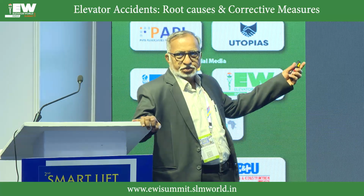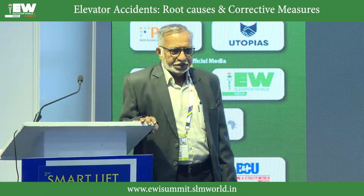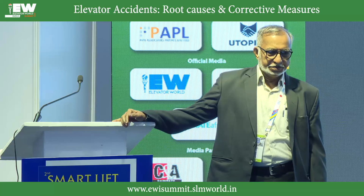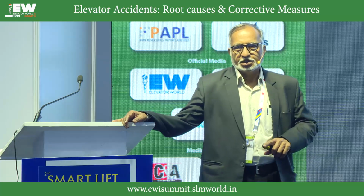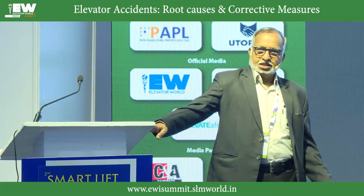The safeties in the elevator, just briefly, are the door locks, mechanical and electrical locking, limit switches, overload that we studied, the door sensor that we also saw in the first session, and the over-speed governor and buffer. These are all important safeties available in the elevator, and still we find accidents, fatal accidents.